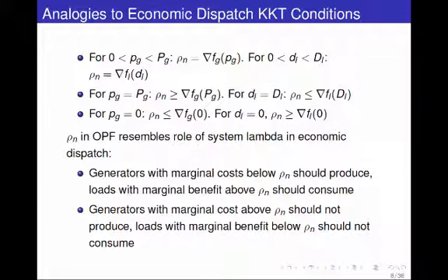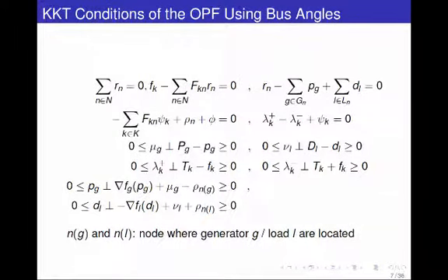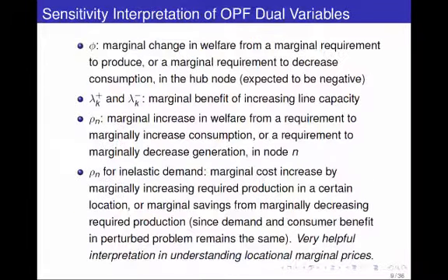But now, the lambda was easy to kind of see the last time. All we did is we took an increasing supply curve, a decreasing demand curve, we took their intersection. That was the best way to dispatch. Now this rho depends in complicated ways on a bunch of other stuff. So sure, it's a threshold for each bus, but how we get it is a different story. And there's a whole sensitivity analysis that you can do. Again, remember these dual multipliers, they correspond to sensitivities of the objective function when you increase stuff on the right-hand side.